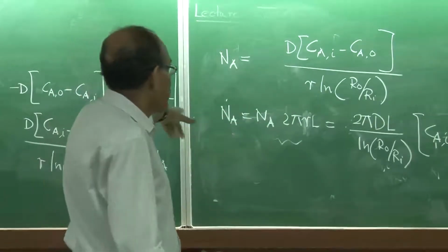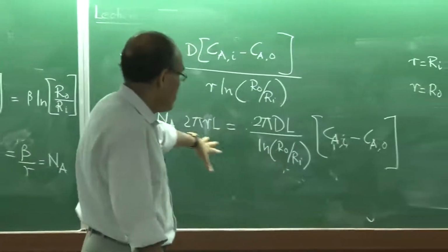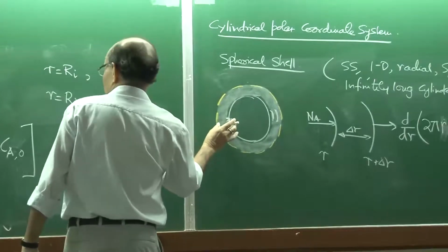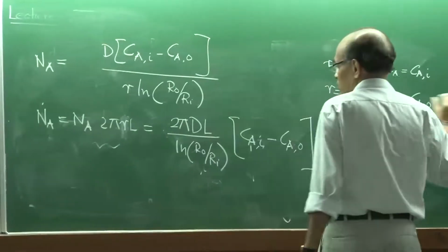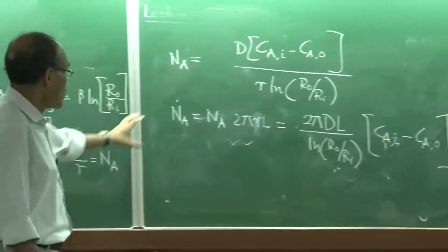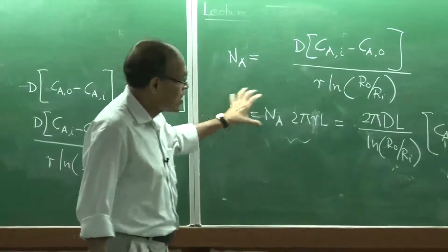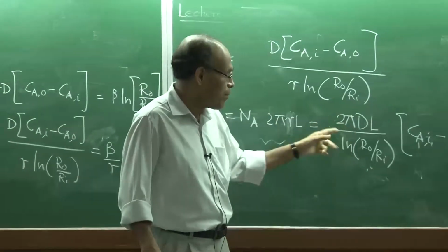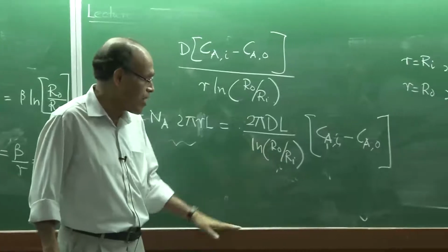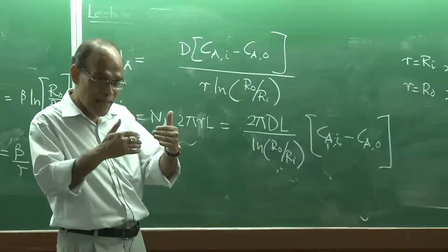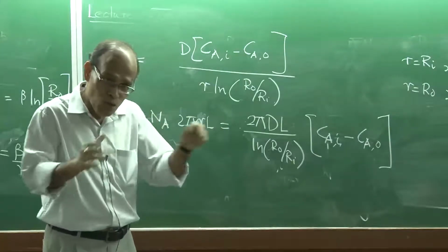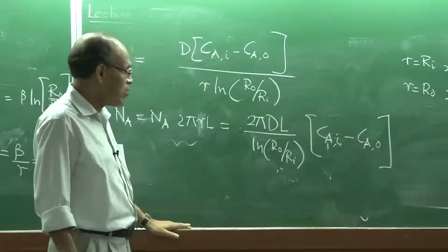And in this case, if the gas is permeating through this, of course this is going to be much more. And this total transport, as you can see, has no R dependence, no radial dependence here. These R's are all constants, inside radius and outside radius, and outside radius minus the inside radius represents the thickness or the path through which the diffusion is actually taking place.